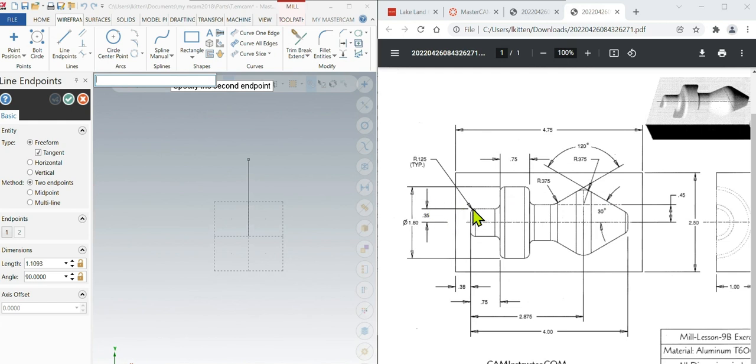That's kind of our long range plan. Right now we have to get up to this corner, okay? And you can see it's 0.35 high. So what number would I type in there for my X and Y, if I'm 0.35 high on absolute? We start at 0. Yeah, 0, comma, 0.35. That's right. See that? So we're just going 0.35 high. That's not too bad, right? Now just hit enter. Okay, so we got that first line done.